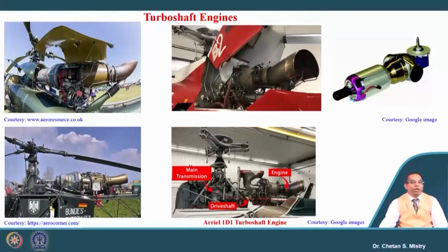So, here if you look, this is our gas turbine engine. You can see here, this is the exhaust. As we have discussed, the purpose here is not thrust generation. So the exhaust we are looking at has a different kind of construction. The gas coming out from this exhaust, or from this nozzle, is at high temperature. So that should not impact the main rotor blade or any other component of the helicopter, and that is the reason why it has a special kind of shape.